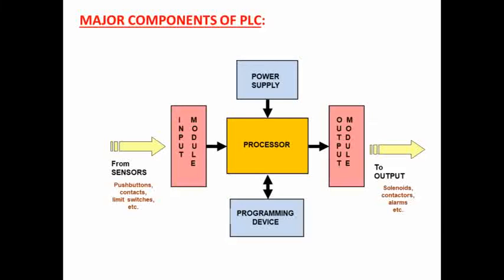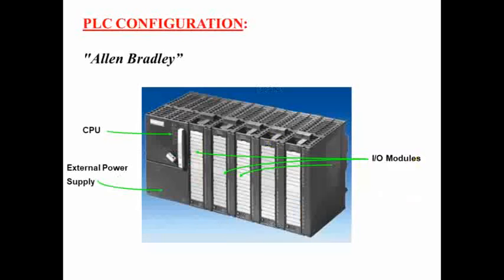A single-ended input suffers from loss of common mode rejection and is very sensitive to noise, and hence analog inputs are connected in a single-ended configuration generally when they are to be used only for the purpose of data acquisition. Differential inputs provide common mode noise immunity, and therefore analog inputs are connected in a differential configuration when both data acquisition as well as precise closed loop control operation is prescribed.